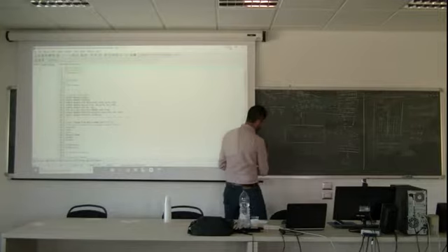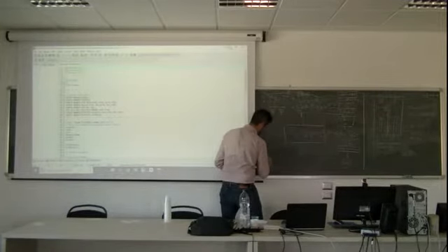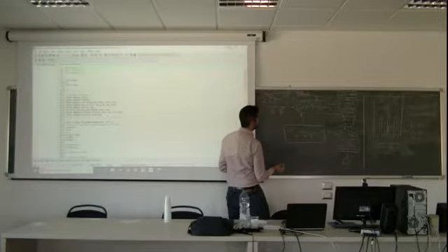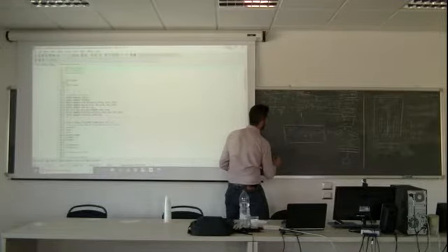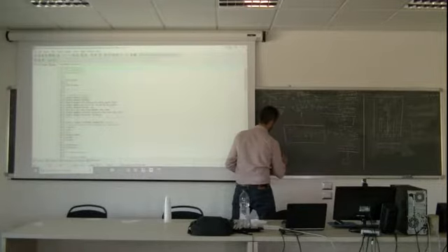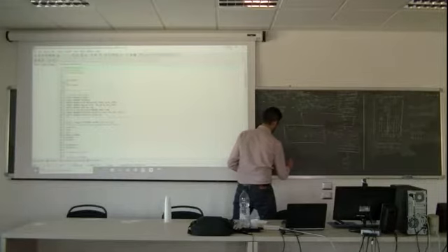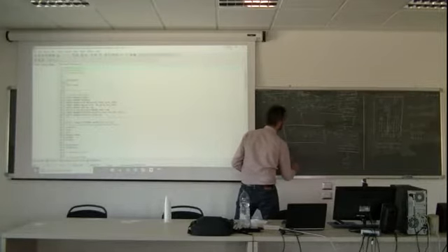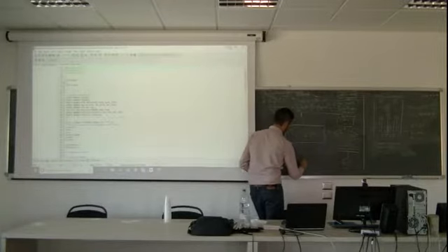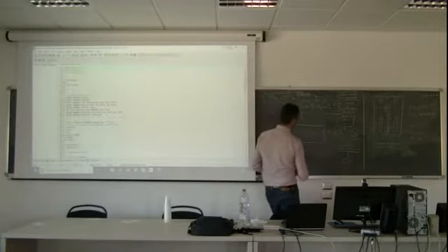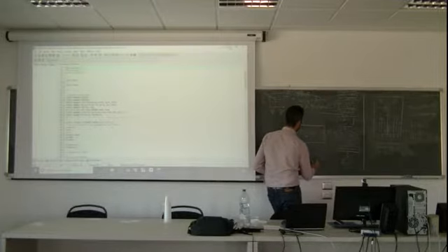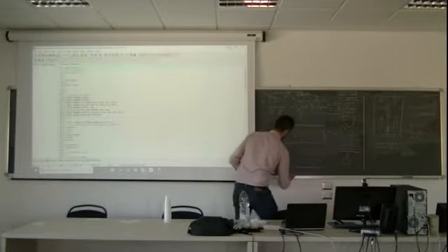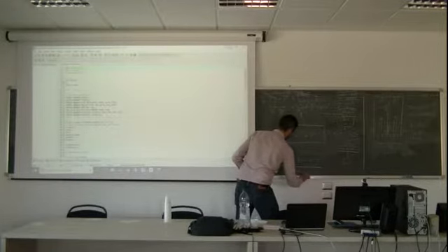I will isolate. In case of i equal to n, TP will be k divided by delta x1 multiplied by T west, plus k divided by delta x2 multiplied by T east, plus qv multiplied by delta x1 divided by 2, and everything divided by k over delta x1 plus k over delta x2.